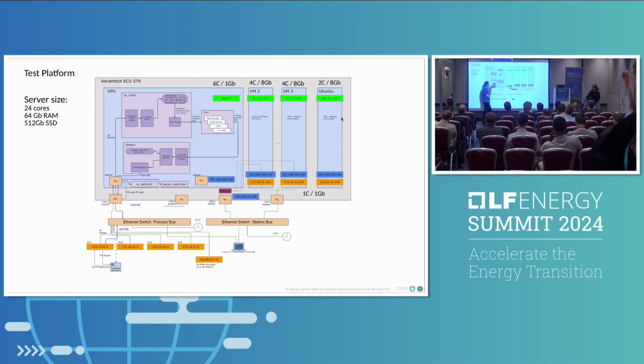This is where the protection algorithms are collecting this data as an input. The protection algorithm executes whatever it has to execute, and it is the one that decides if the power is stable, if it is needed to trip, if it is not needed to trip, etc. The rest of the blue boxes are other virtual machines.